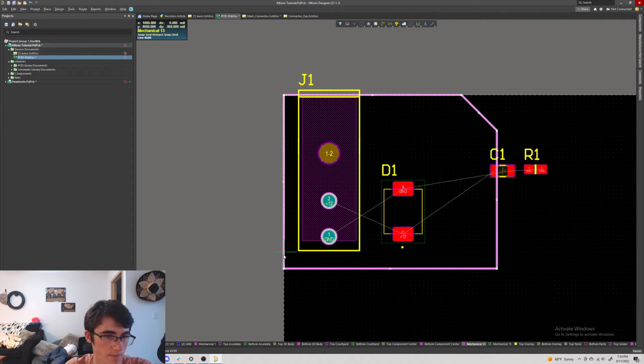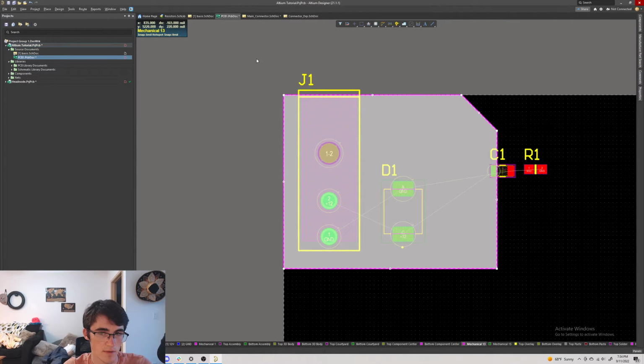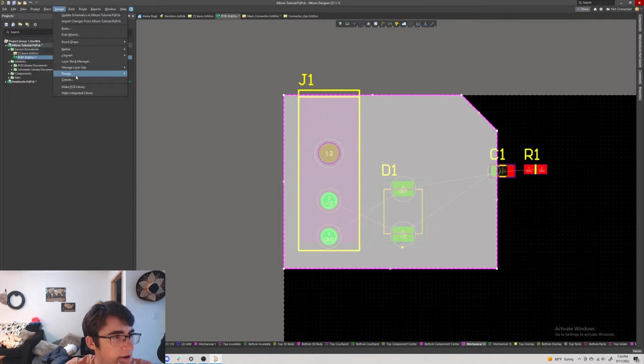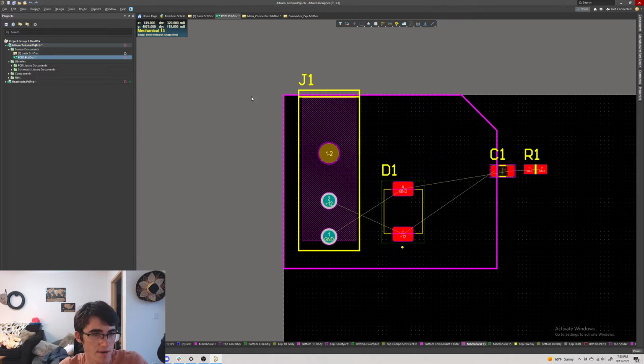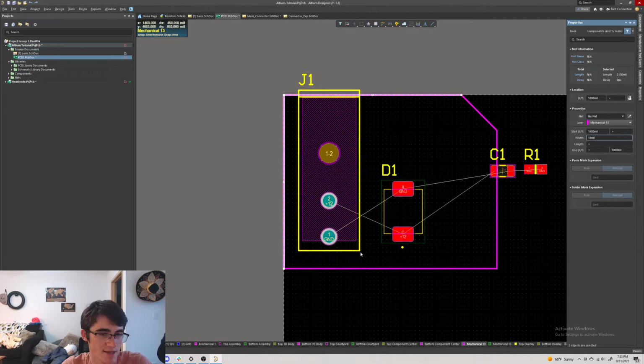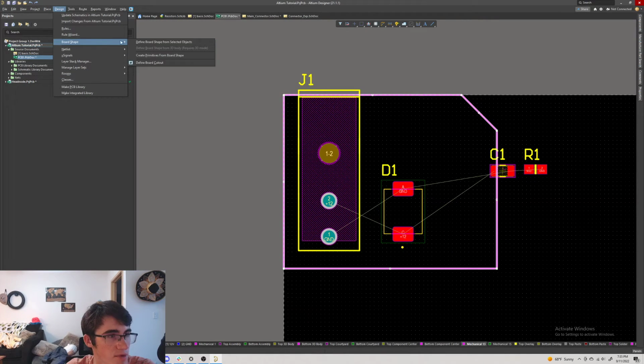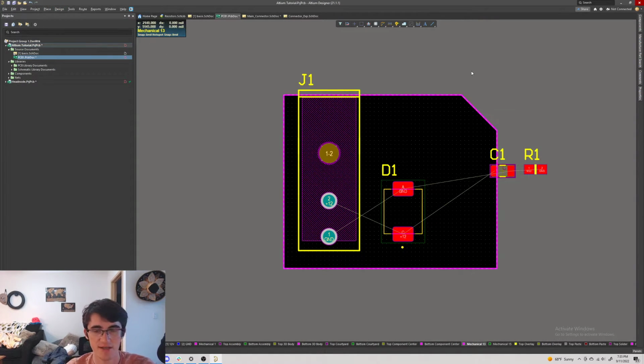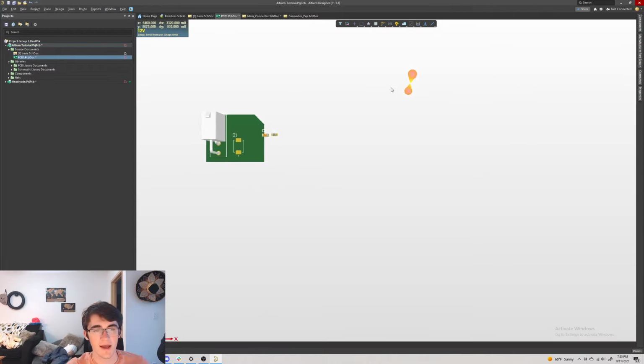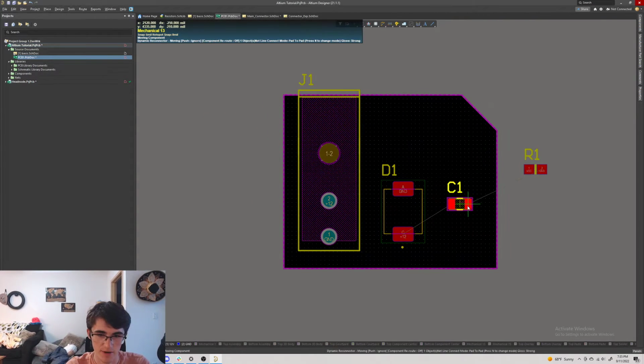Oh yeah. Then you can select, pretty much what you do is after defining the board cutout, yeah, it'll highlight it for you. And then, oh, no. Okay, I messed this up. Sorry. So you select these. I think you can do it that way too. I think I have before. You go to design, board shape, and then define board shape from selected objects. And now you'll see that that PCB size got way smaller here, but that's okay because we only have 4 parts.